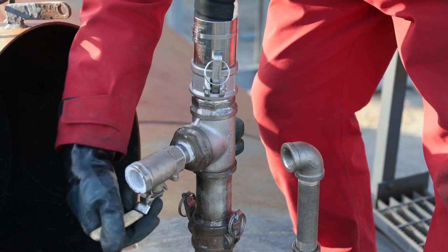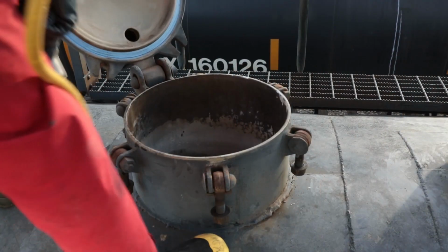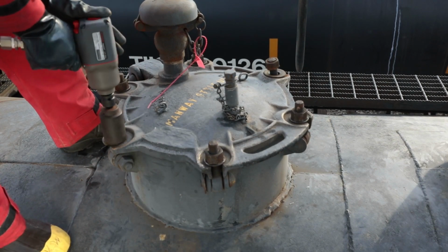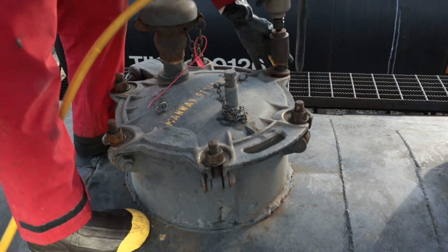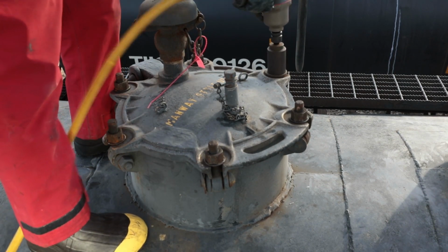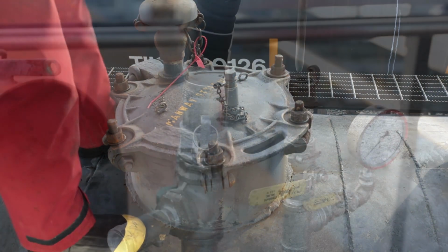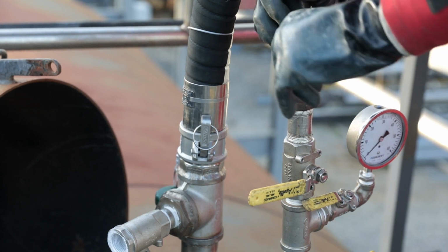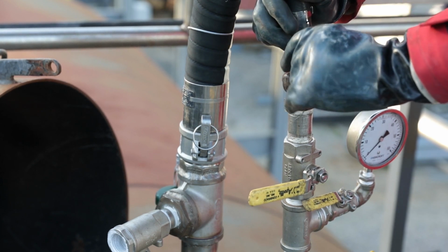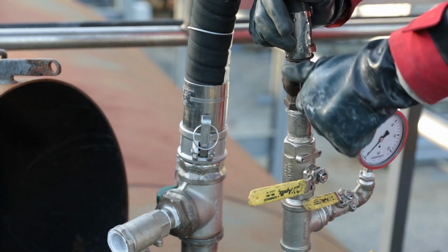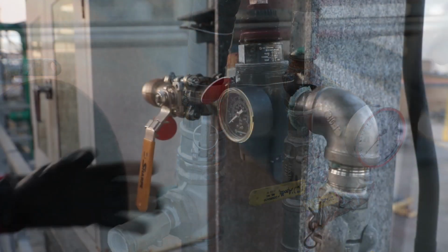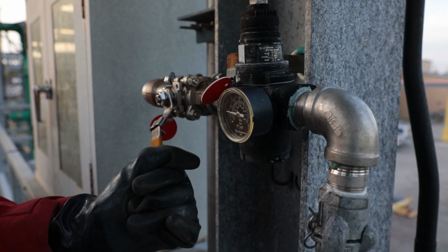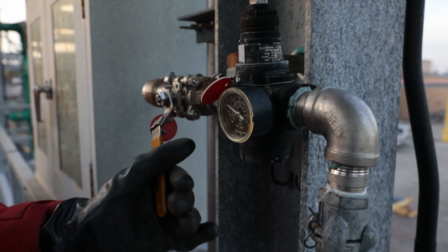If a retain sample was taken, close and tighten the manway so the gasket seals properly. Attach the compressed air manifold to the tank car air valve. Slowly open the compressed air valve to increase the pressure into the tank car up to 25 psig.